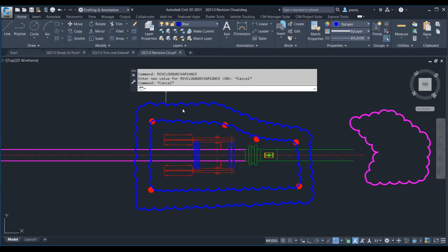So if you have an AutoCAD XREF or multiple external references loaded to the base drawing, and you need to track the changes between the latest version and what you have in the drawing, you could use the XREF compare option, similar to the DWG compare.